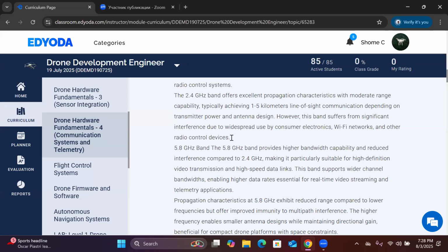In order to avoid that, we need to optimize the signals. So that is why the adjacent channel optimized receiver topology or technology is being used in the UAV architecture. So what is the significance of this adjacent channel optimized receiver? This adjacent channel optimized receiver will be responsible to mitigate the co-channel interference, because when you are transmitting a signal at 2.4 gigahertz from the communication module to the communication box or the ground control station, co-channel interference will come into picture.